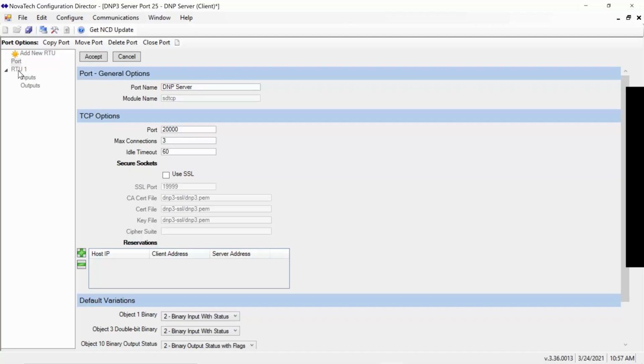So that works well if maybe it's the same utility and A, B, and C are just redundancies of the same overall system and they share a common database, etc. Now, if it's the opposite case where those different sites are perhaps different utilities, maybe there's a shared RTU inside of a substation and that data needs to get to all of the devices, it's not necessarily going to get all of the buffered data until maybe integrity scans come down, per se. But at that point, you could come back to the idea of copying the ports.